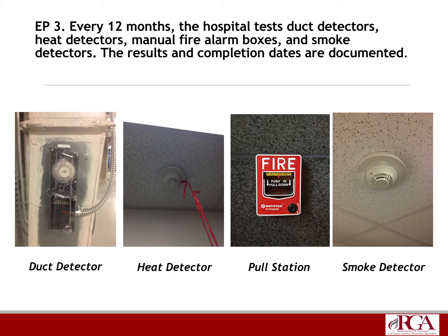EP3, every 12 months, the hospital tests duct detectors, heat detectors, manual fire alarm boxes, and smoke detectors. The results and completion dates are documented. Now, this is basically the bulk of your fire alarm system. Your duct detectors, your heat detectors, pull stations, and smoke detectors.